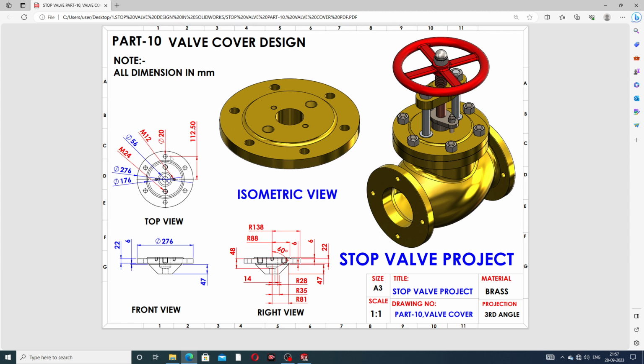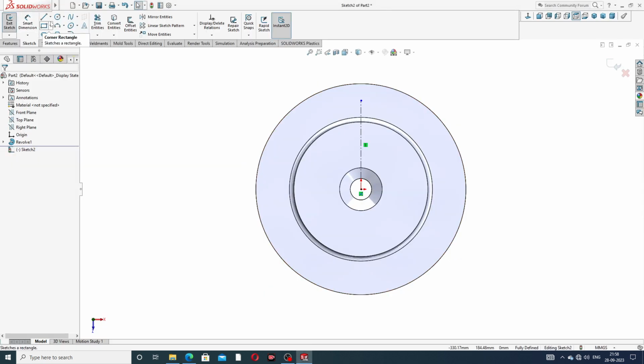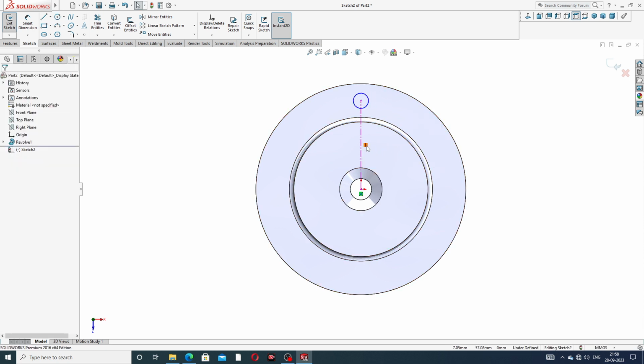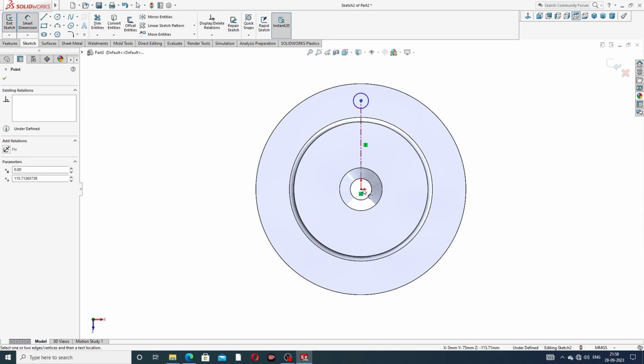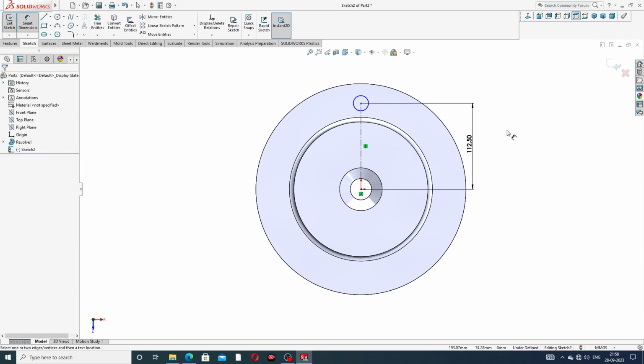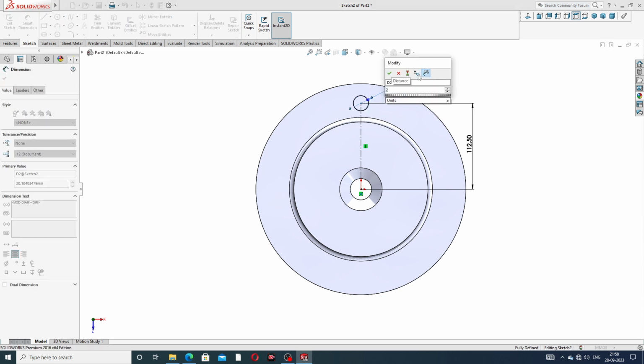Okay, and this is perfect. This distance is mentioned here, but apply a thread and then the distance is 120. Okay, and use a circle drawn here, and this is a vertical line, and this distance from this point to this is 112.5 millimeter, and this diameter is 20 millimeter.